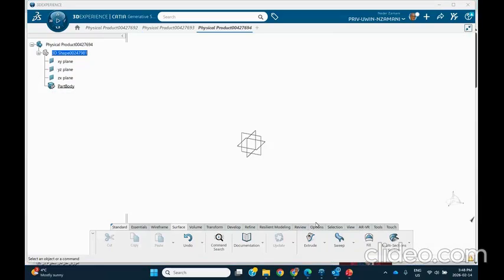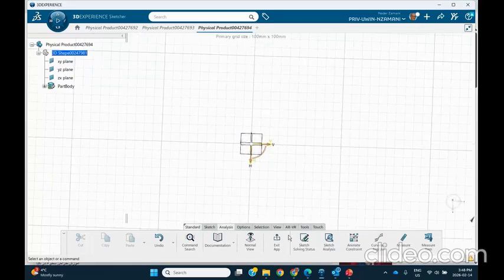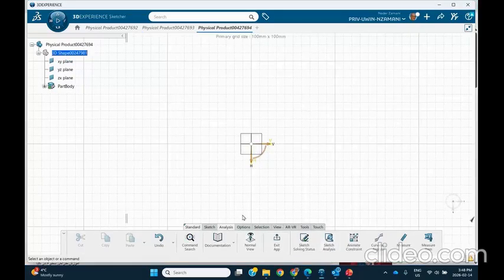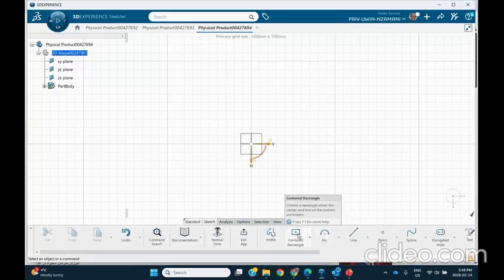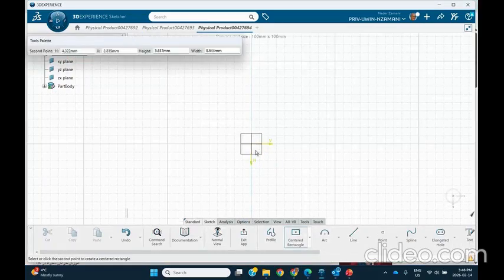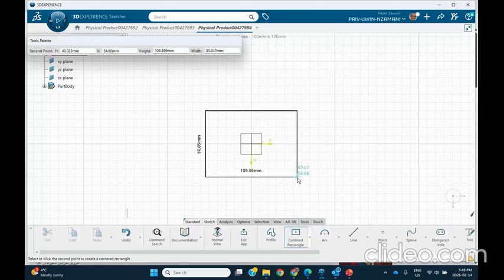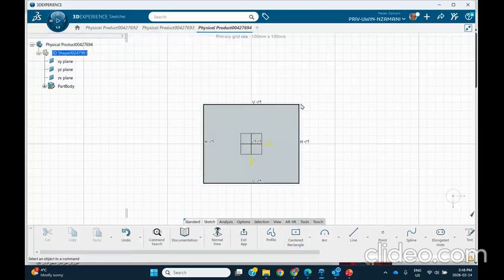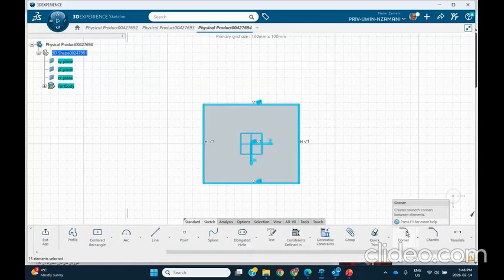In my second example, I'm going to make a surface that looks like an accordion, and I'm going to ignore all the dimensions. So let me first of all draw a rectangle on this face. This is going to be the guide later on, as you'll see. So I'll use a centered rectangle to make my job easier, like this. Okay. And then I want to put corners here. The easiest way is to select this whole thing and then go to corner.